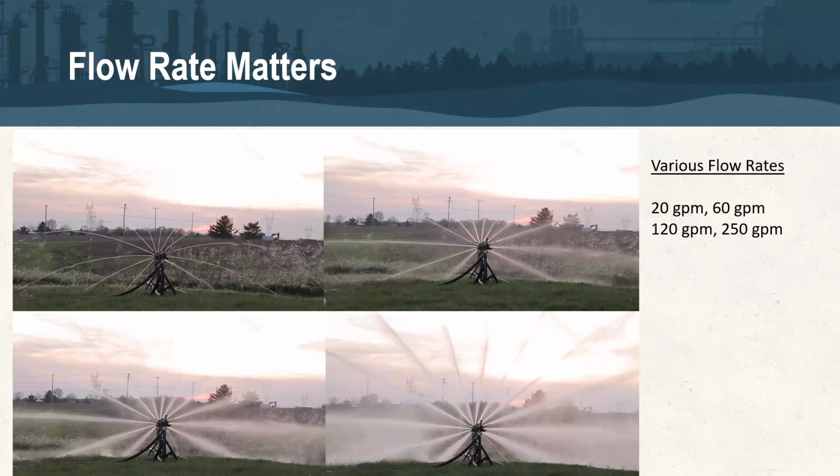So this is just an example of one of our pumps called a triplex hooked up to an overburden injection tip and chained to a sawhorse here. And we're just showing you at different flow rates what this distribution is giving you and why we're doing it. And you can see that the intent here is to be both specific with loadings in the subsurface, but also create that vertical and lateral interlapping, interleaving and overlapping in the subsurface.